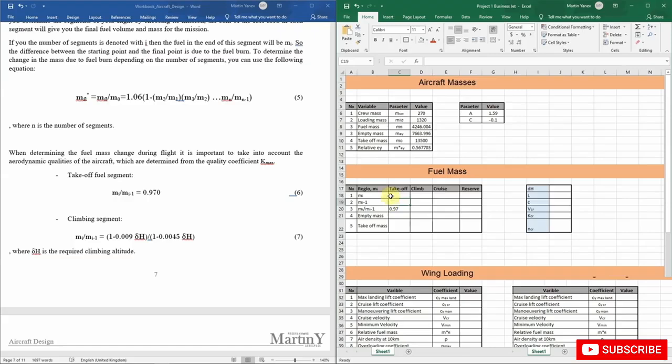And then also the previous segment, before the aircraft takes off, is when the aircraft has its full mass and the full fuel tank. Okay, so this will be the full mass of the aircraft. So mi minus 1 should be the previous flight segment. So here we have the full mass of the flight, because before the takeoff the aircraft hasn't performed any action, so all the weight is on the aircraft in the segment before the takeoff, if it makes sense for you.